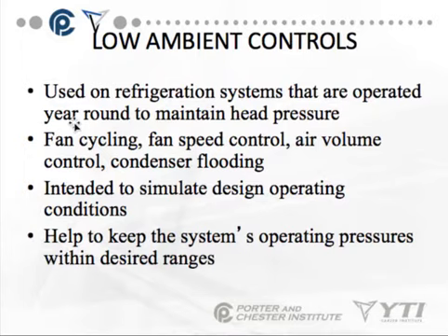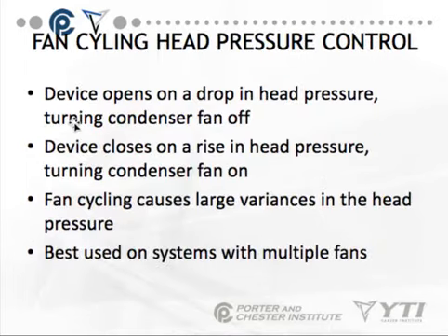What they do is they're also known as fan cycling, fan speed, air volumes, or condenser flooding controls. They're intended to simulate design operating conditions. They keep the system's operating pressures within desired ranges. The device opens on a drop in head pressure. Okay, if the high pressure drops too low, it's going to open a switch and turn the condenser fan off. As the head pressure, the high pressure, rises, it closes, turning the condenser fan back on.